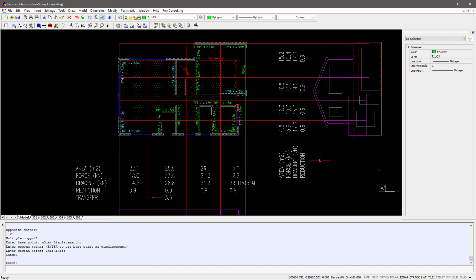Here we have our bracing completed going east to west. At the eastern end, everything is pretty standard. We've got our bracing at the corners and along some central walls. In one of the garage walls, we needed to put some type 4 in, as there were no other walls in the area. Something you may have noticed is that at the western end, there aren't really many walls that we can use for bracing.